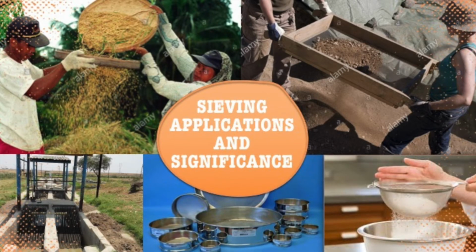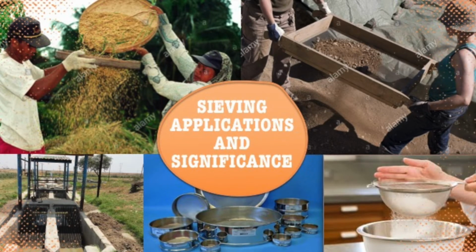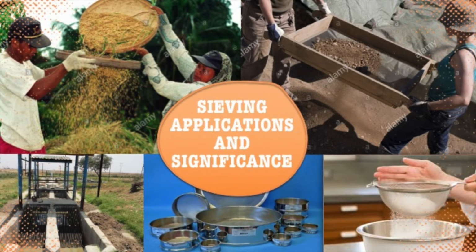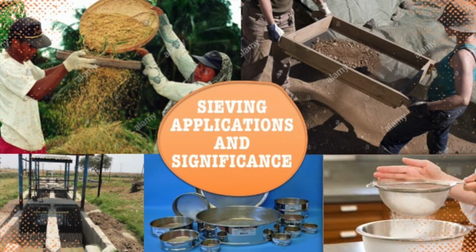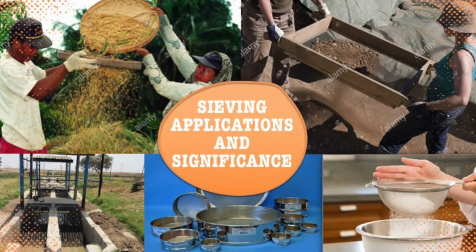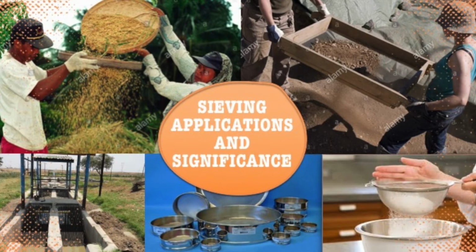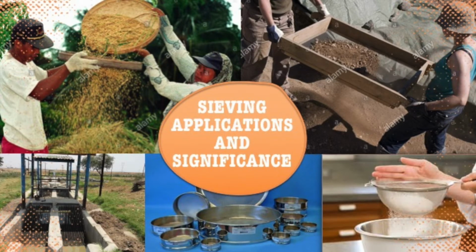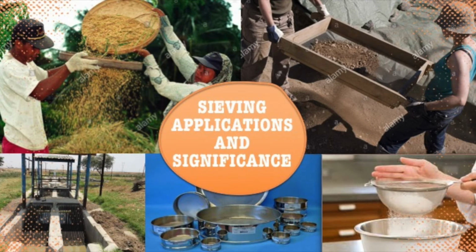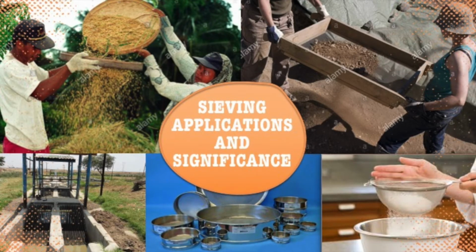From a chemical engineer's perspective, the same concept is used in one common industry that we may venture into in the future. Screening is the first unit operation used at wastewater treatment plants, as shown in the image at the lower left corner. Screening removes objects such as rags, paper, plastics, and metals to prevent damage and clogging of downstream equipment, piping, and appurtenances. Some modern wastewater treatment plants use both coarse screens and fine screens.